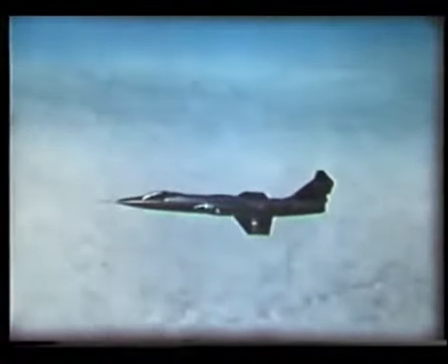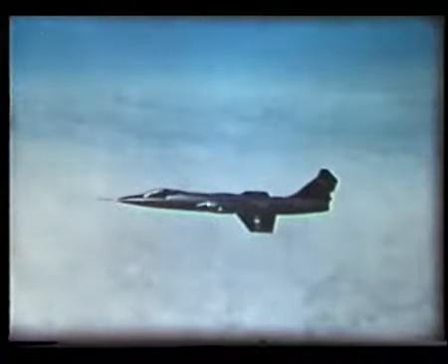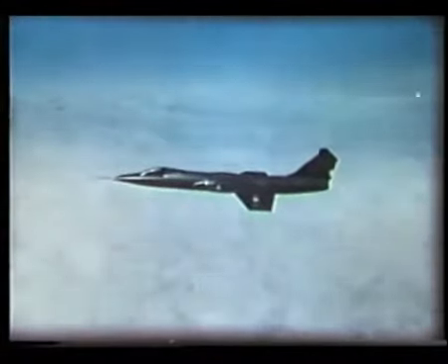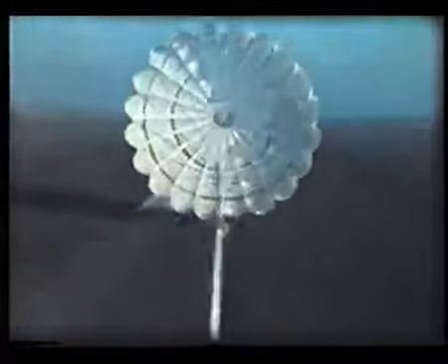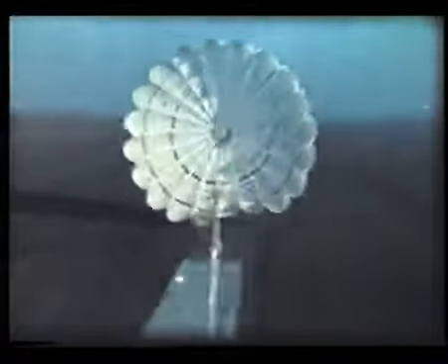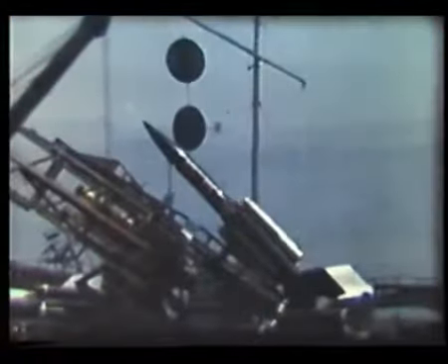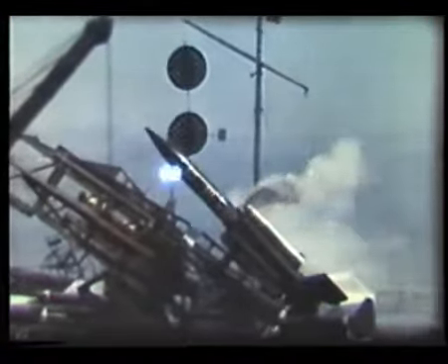At supersonic speeds, a high lift coefficient is not needed, as the speed is high enough to give the aircraft the lift it needs. But a low lift coefficient brings severe low-speed problems, high stalling and landing speeds. So very long runways and sometimes extra braking devices are needed for aircraft with these supersonic wing sections. Some missiles use straight wings without sweepback, with double wedge or biconvex sections. So do some supersonic aircraft.